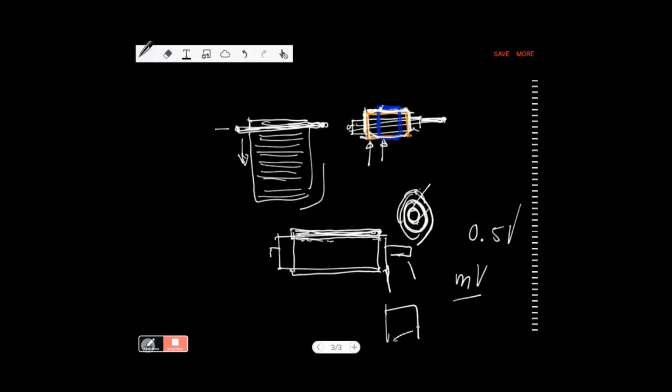When you simply put a test probe, your voltmeter, on the paper and on the copper, you only read around several millivolts. However, when you put the test probe on the aluminum, you'll get beyond the millivolts range, usually somewhere in the 0.5 volts range, simply because your aluminum is now covering almost the entire length of the paper. We don't cover everything to avoid a short circuit going to the nano-coated copper, but just enough for the paper to come out on the other side.